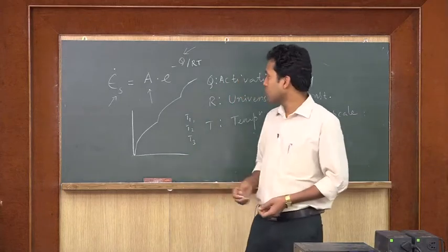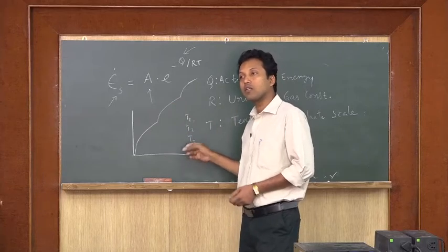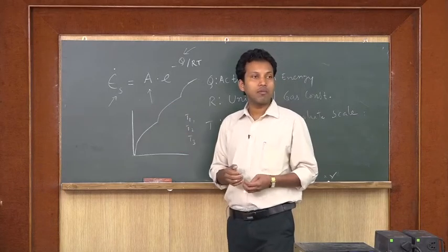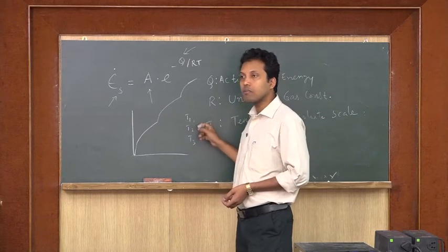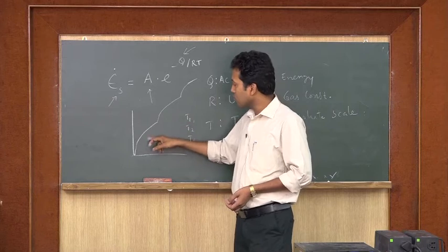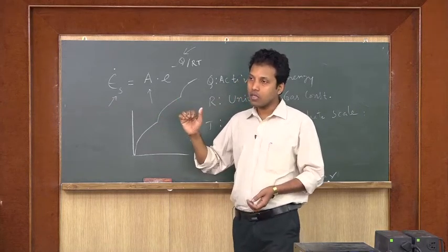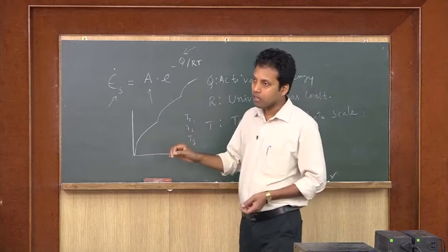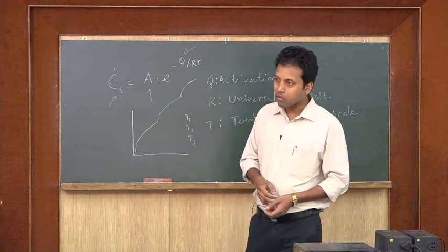Now, for calculating the activation energy, we should not vary the temperature so much that the creep deformation mechanism changes. So, we will make small changes in the temperature, and then we will have different creep behavior under the same mechanism. Different in what terms? Only the steady state creep rate will vary.